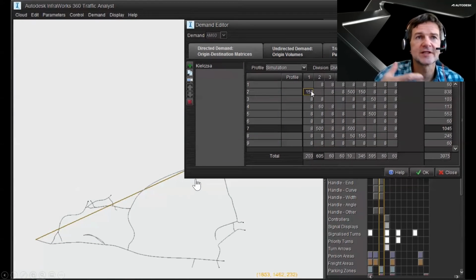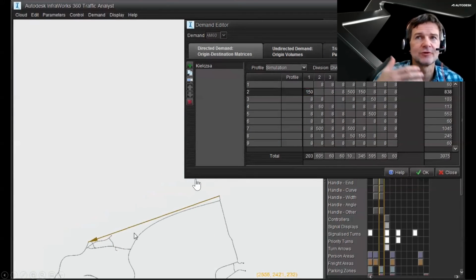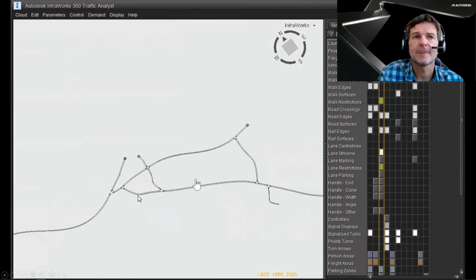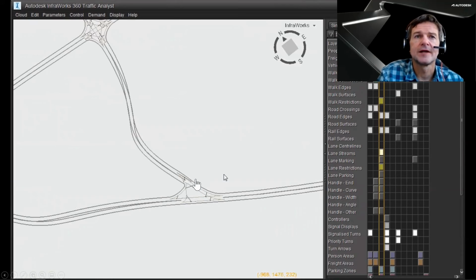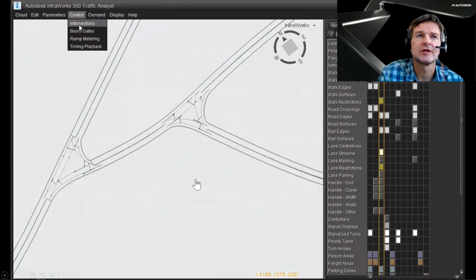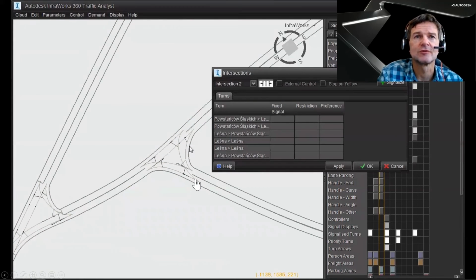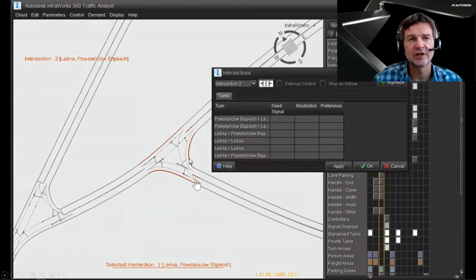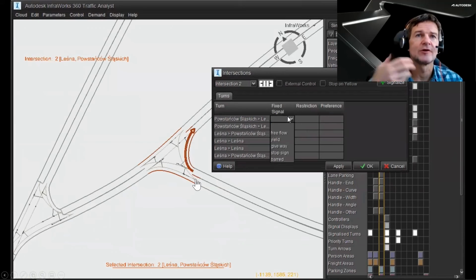Of course, these cars will need to travel there, so you are adding additional traffic to this road. So you have to specify all that kind of stuff. And then let's have a look at some intersection. You can specify in the intersection, as I mentioned, different turns from which direction to which direction, because from GIS data you also have the name of the streets or the name of the road.